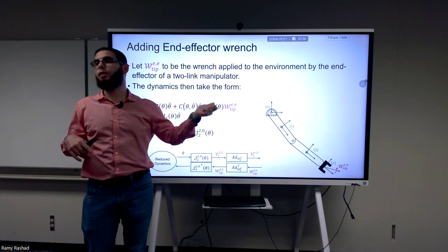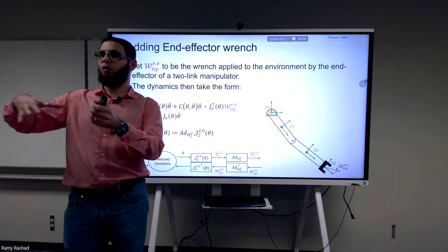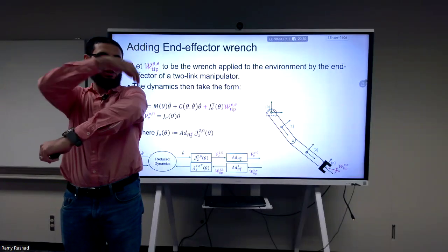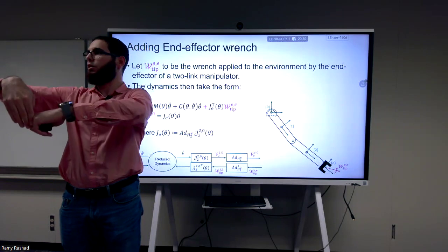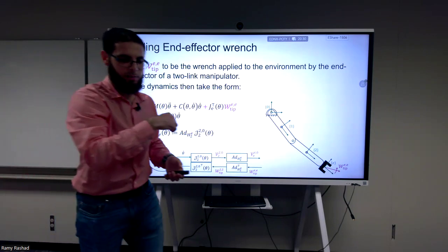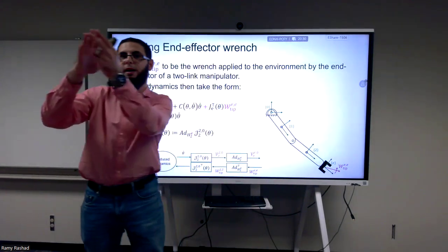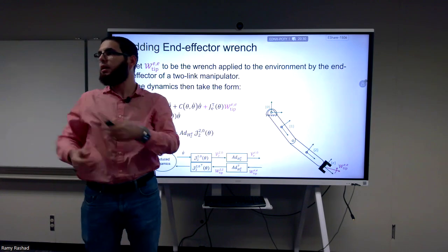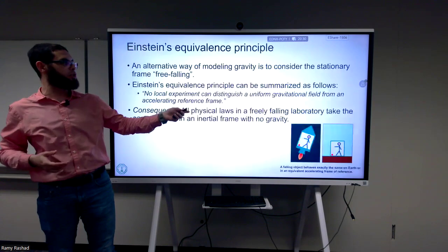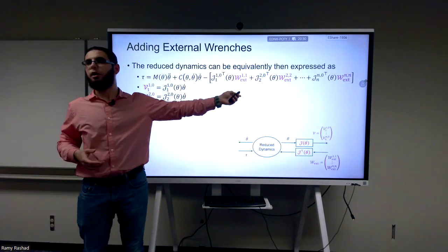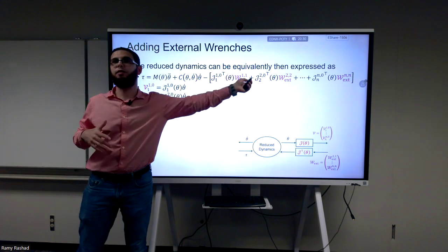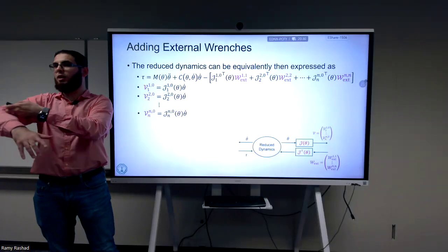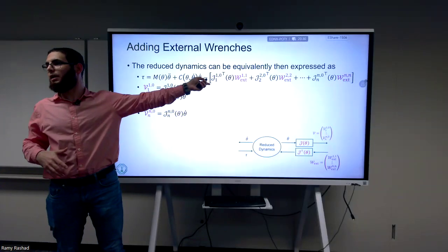If you have interaction not with the end effector, for example, if you have what's known as collaborative robotics, so co-robots, if you have a co-robot, then this robot, I can touch it also on the hand, right? Or I can touch it here, right? So, for example, I might do manipulation by pushing this bag like this, not just with my end effector. So I can, in principle, interact with any of these links, right? With any of my links. How will the corresponding equation change? You just go back to this expression and you look at it and just transform any one of these, depending on which one you're interacting with, okay? So if you have a robot that interacts with multiple links, it has multiple contact points, it's easily extendable to this case.